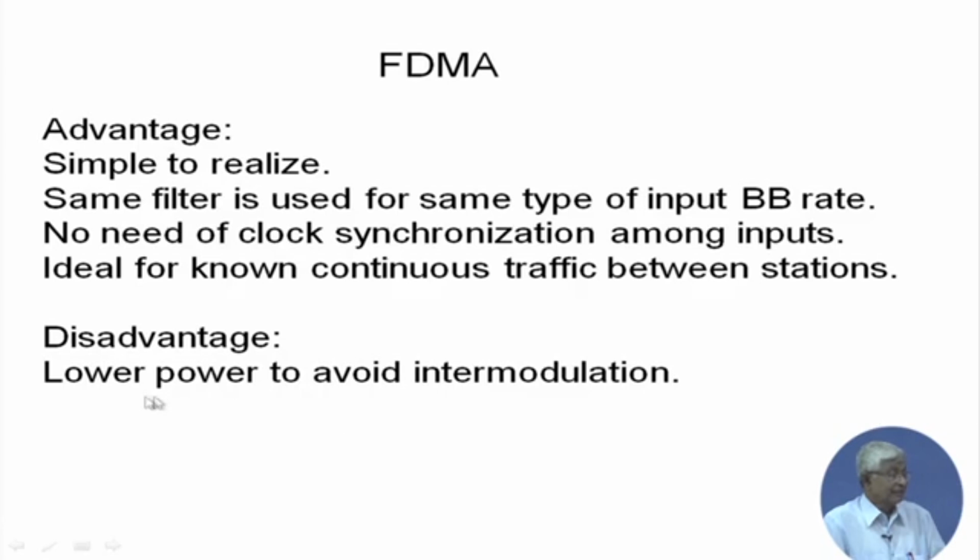So, that is one of the problems of FDMA operation. That is why in the trunk route it is used, where larger stations are there, only a few of them, larger stations where you can increase the gain of the antenna by sizing the antenna larger, and temperature also can be controlled.